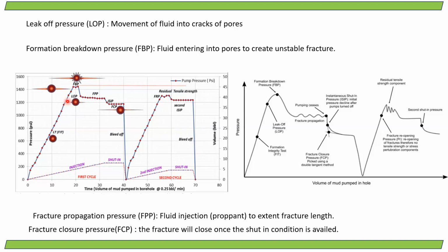So once the deviation happens, the fracture volume will start to increase while accepting the fluid into it. In that way, the pressure will start to deviate, and finally it will reach a position where the fracture will burst, like the channel will burst into a fracture. Once that huge volume has been generated, the hydraulic fluids flow very smoothly, but it requires more volume of fluids to enter to maintain the pressure. So the pressure will immediately drop.